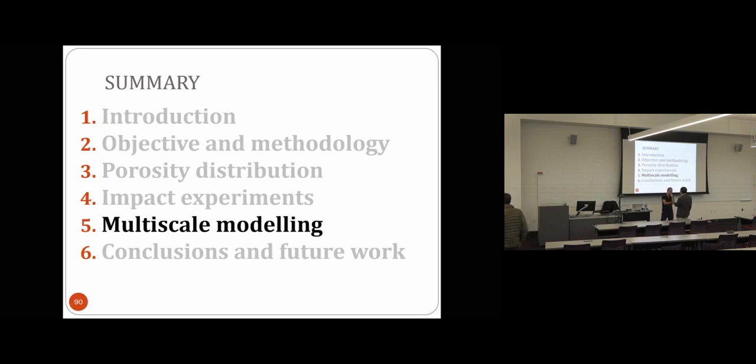Additive manufacturing methods with porosity would be really good at it. In compressive loading, you have the wave and it's dissipating. This is very cool because instead of having a very thin front, the front is getting submerged. That dissipates energy, decreases the intensity of the shock, and with porosity, you can reduce the amount of fracture.